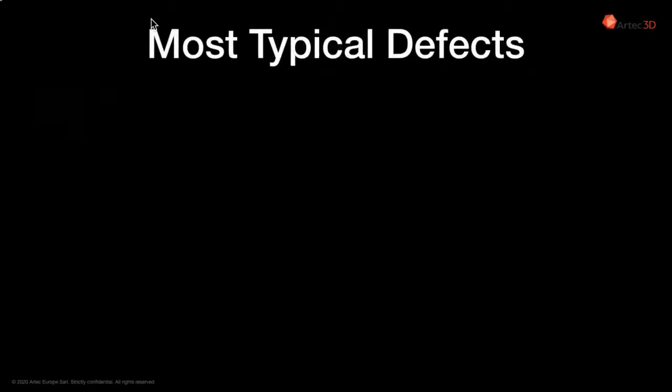So, the most typical defects you may see during production. Missed components, it's easy. For some reason, the component was not placed on the PCB, or maybe washed out by the heat of the instrument or another component, if your design does not meet the capabilities of the machine.